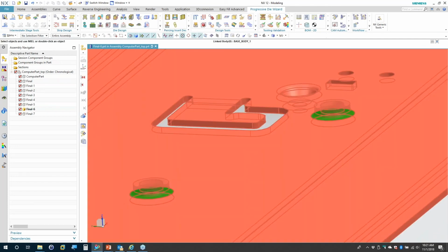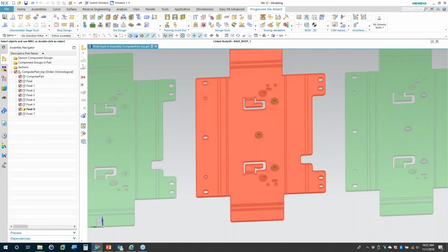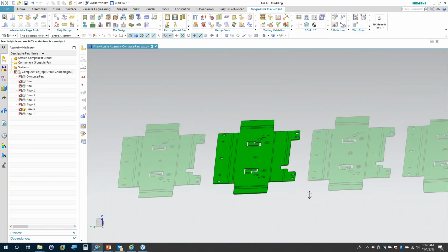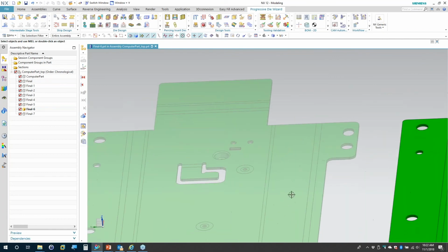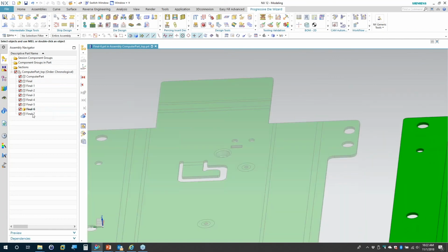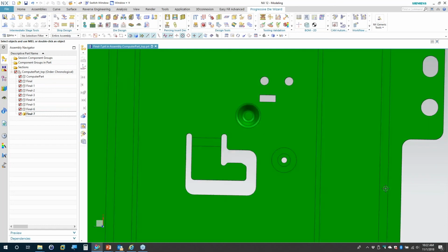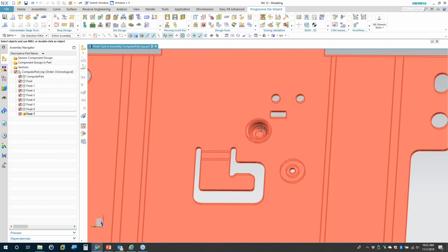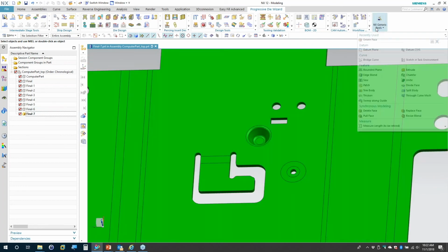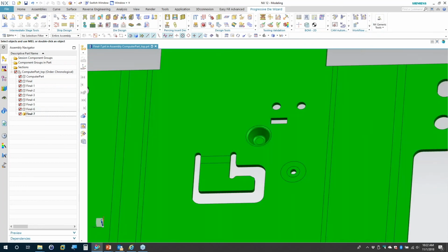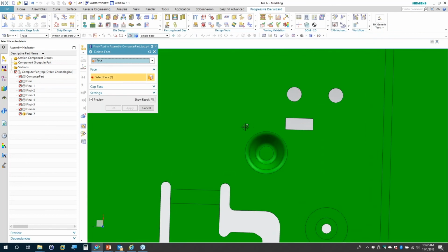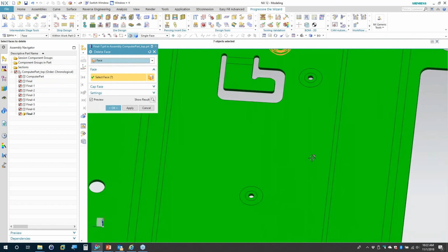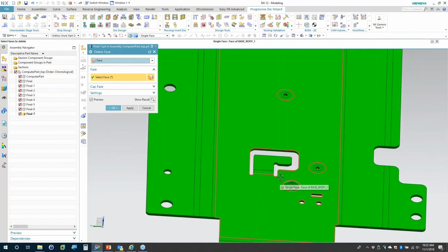Okay. So we're back down here, and then finally when we get towards the end, this final stage, we've got some dimples in here, and just like with the beads, these dimples are essentially drawn or punched out of that base face. So I'm just going to use synchronous modeling again, and we'll use the delete face tool here and get rid of those faces and get rid of these faces down here.